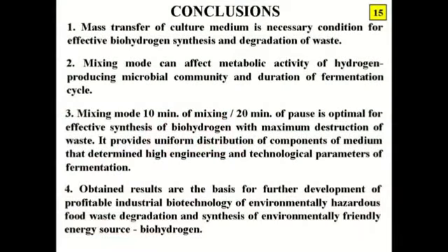So, as a result, we can draw the following conclusions. Mass transfer of culture medium is a necessary condition for effective biohydrogen synthesis and degradation of waste. Mixing mode can affect the metabolic activity of the hydrogen-producing microbial community and the duration of the fermentation cycle. The mixing mode of 10 minutes of mixing and 20 minutes of pause is optimal for effective synthesis of biohydrogen with maximum destruction of waste.